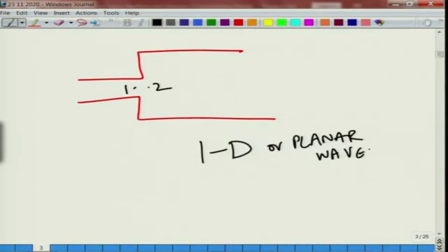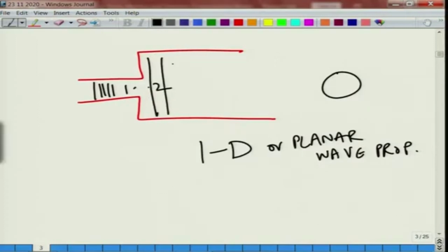So, what is the consequence of such an assumption? As we can recall from our very first lectures of this series, when we have a wave whose phase is constant over the cross sectional area, that is, if you are in the small diameter tube, across the cross section the pressure as well as the particle velocity normal to the plane are all constant no matter at which point you are in the section. So, similarly the same logic applies here.